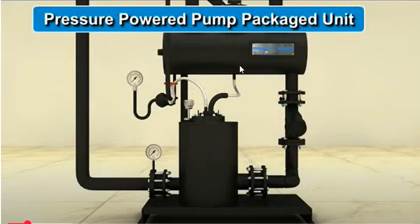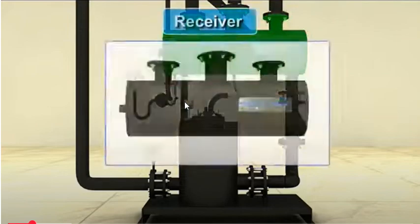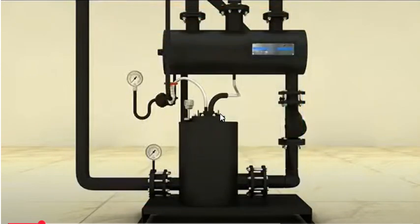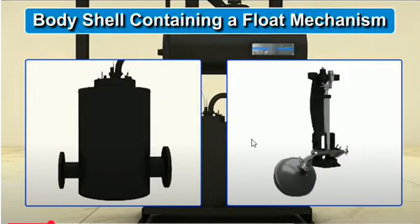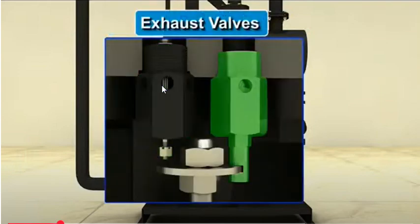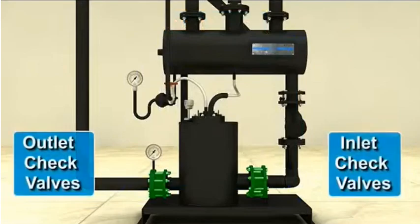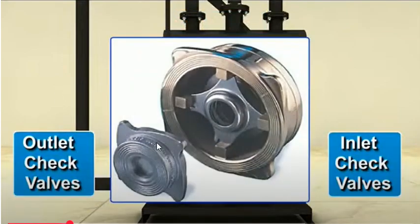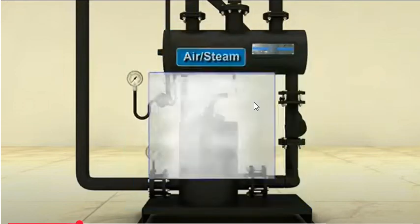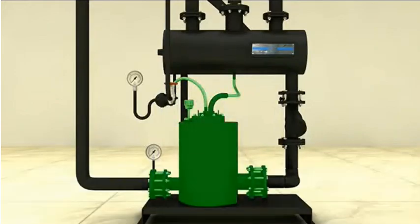This is the pressure powered pumping unit, and it consists of the receiver, the isolation valve, strainer, and body. The body contains the float mechanism, and this is the motive air inlet and the exhaust valve, and these both are check valves. Air or steam are used as the motive media.